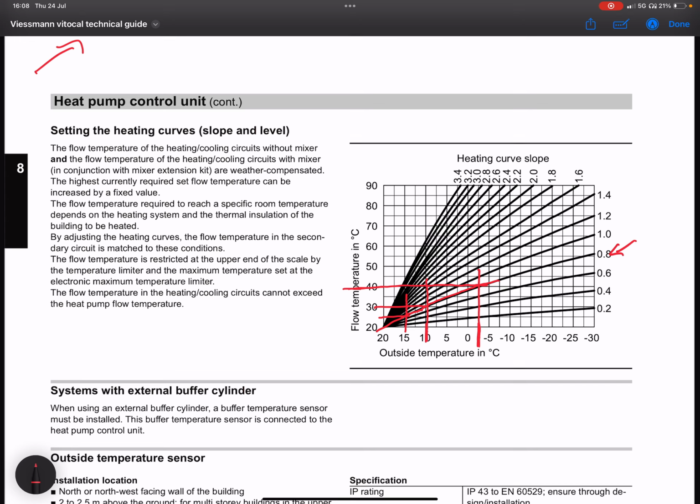In recent years, that has come down, and gas boilers can run brilliantly at 55 degrees, and often radiators do not need changing for the most part. But it's still trying to put out that same flow temperature no matter what time of year it is. It doesn't take into account this changing flow temperature we get when these axes meet at different outdoor temperatures. And the reason that's important, especially for heat pumps, is they are known because they can get 400 to 500% efficiency, and they will only get that with a weather compensated control.